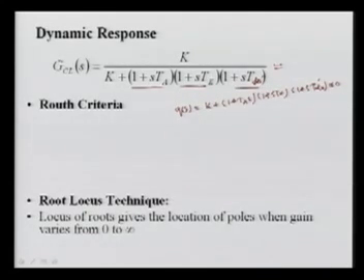We equate this to 0 and then go for the Routh criterion. For the general case, if the equation is of order n, although this is order 3 only, we write the coefficients corresponding to s^n, then s^(n minus 1), and so on, and finally s^0, which is a constant. We form the array and look at the first column, and that gives you the necessary condition.